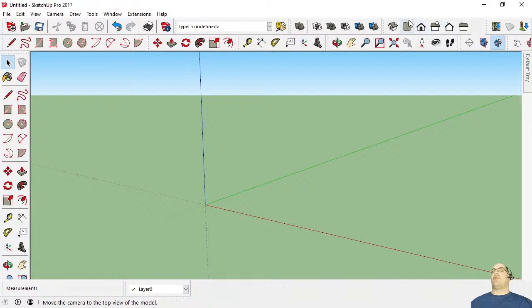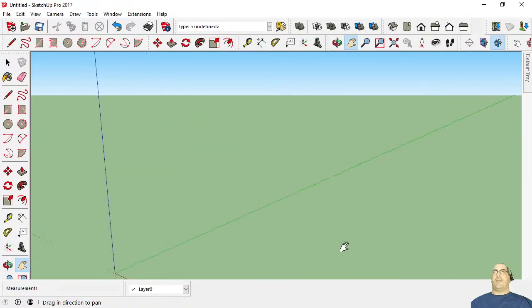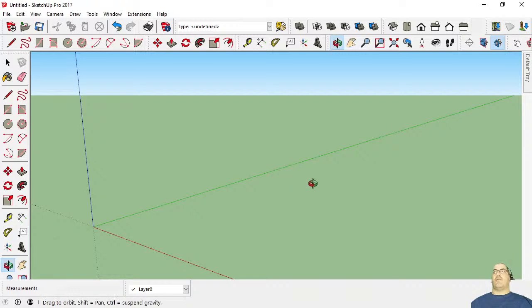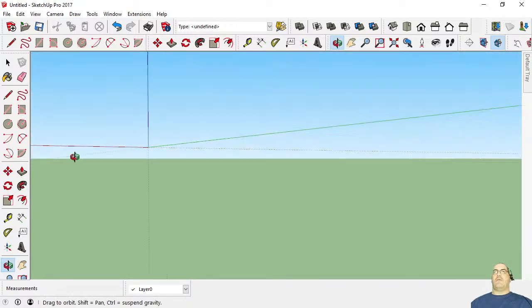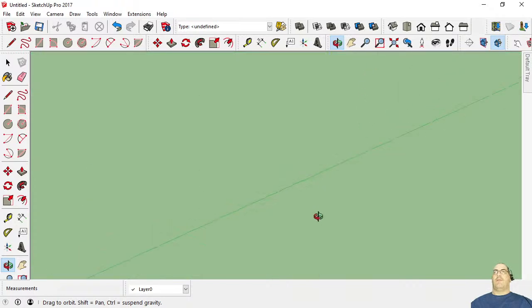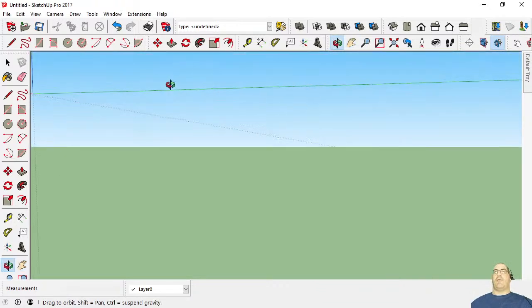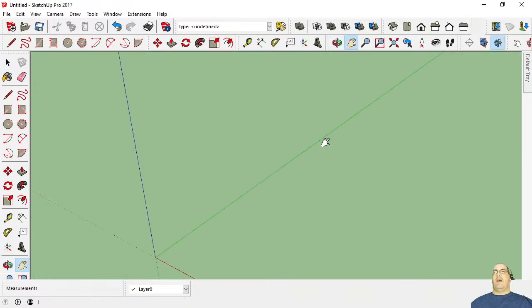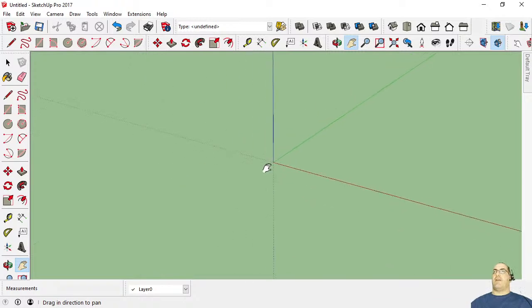Now, as well as being able to show you different views, you also have your movement tools here as well. Your pan tool pans you around your scene. Just select it and drag it. Your orbit tool allows you to orbit round your model. Now typically what you're going to do most of the time is have pan on, use your left button with that, and then click your middle button to do the orbiting, and then use your zoom to zoom yourself right out from your